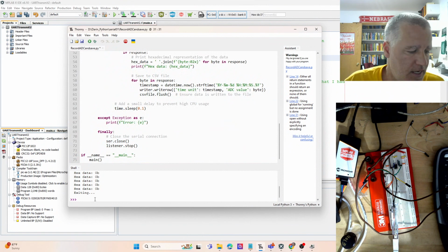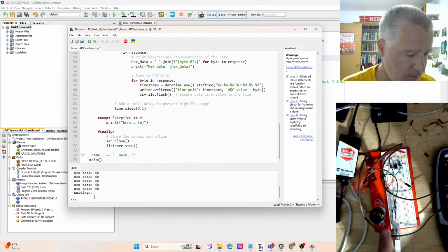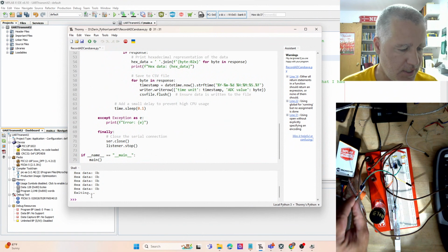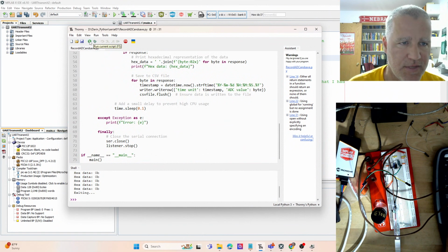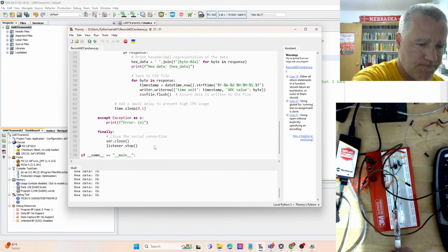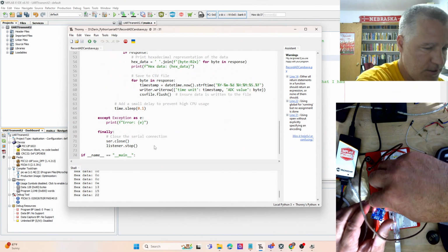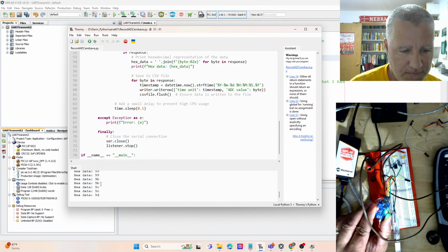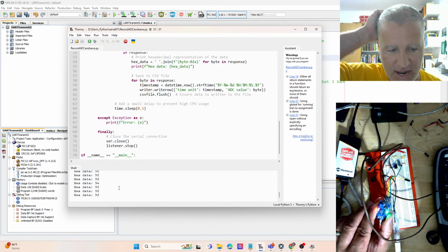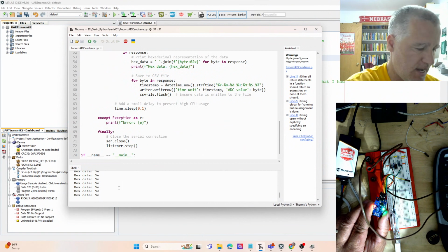All right, and so then we'll just run this. We should see data coming in. Then I'm going to take some ethanol, and we'll expose the sensor to the ethanol, and we'll see the voltage change. So let's go ahead and run this. And so now we're getting kind of a baseline. Now we'll expose this to the ethanol, and we can see here the change in the voltage. And it's now kind of maxing out. It's been now exposed to the headspace of this vial of ethanol.